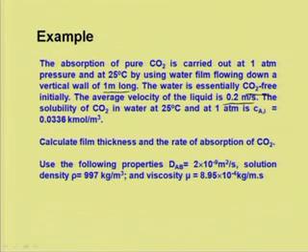The solubility of CO2 in water at this temperature and pressure is given as 0.0336 kilomole per meter cube. Calculate the film thickness and the rate of absorption of CO2. The physicochemical properties, diffusivity, density and viscosity are given.